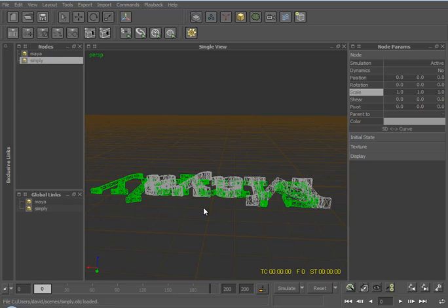It's the same for moving objects around. W will move the object, E will rotate the object, and R will scale the object. If you've used Maya again, it'll be very familiar to you, as it's the same hotkeys. Q to go into object selection mode, and these are all up here as well. Object select, move, rotate, and scale.